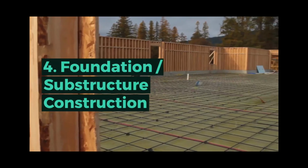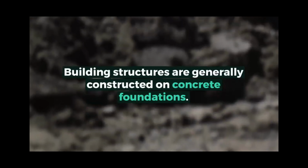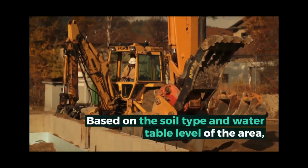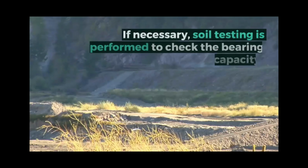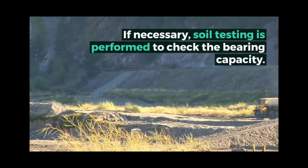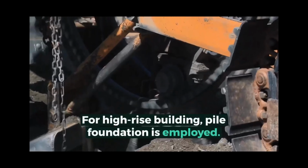4. Foundation or substructure construction. Building structures are generally constructed on concrete foundations. Based on the soil type and water table level of the area, the foundation chosen can vary. If necessary, soil testing is performed to check the bearing capacity. Shallow foundations are required for low-rise buildings. For high-rise buildings, pile foundation is employed.